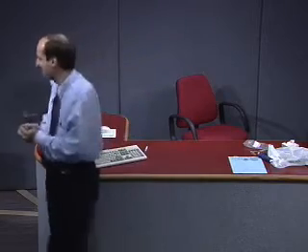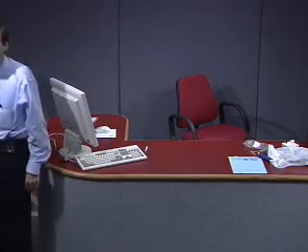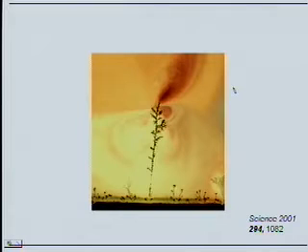What you see here is actually something that Ketan does in his research, assembling microwires from metallic nanoparticles in suspension by using dielectrophoresis, by using an alternating electric field. And we're going to study dielectrophoresis later. So what you see here, these are the metallic nanoparticles, whose original color should be pinkish, but it looks kind of grayish on that screen. You can see that the particles have accumulated in front of the growing microwire, which is the effect of the dielectrophoretic force. This is the electrostatic force which brings them to the tip.